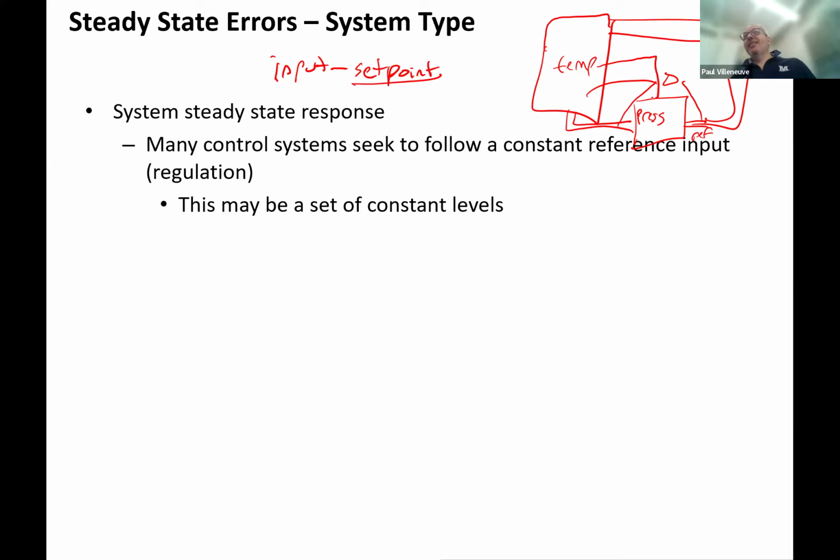Maybe not the best, because you got to send somebody out there and they got to say, well, it's about at this line over here, and you're squinting at it. But sometimes those tried and true things, right? They always work. And especially for you, where you're going to be going, it's always nice to be like, why is this pressure transmitter telling me the tank cannot be 80% full? So what you do is you get your butt out to the field or the floor and go see